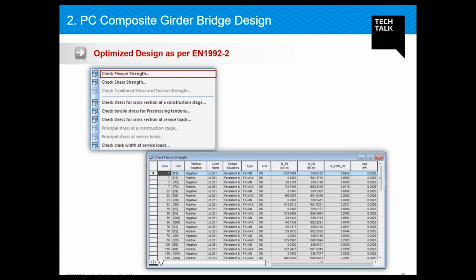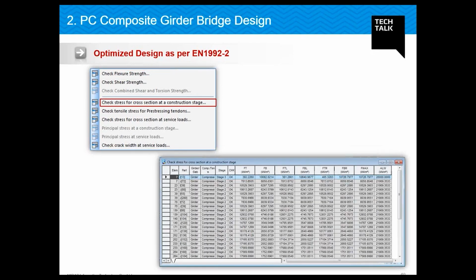If we want to consider the crack of the concrete for the deck, like in the negative moment region, that can also be considered in MIDAS Civil. If we consider the cracked section in the section manager, then we can also simulate the crack in the negative moment region section. We can also verify the stress.